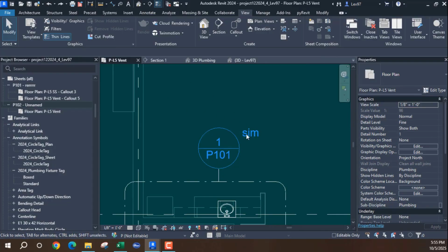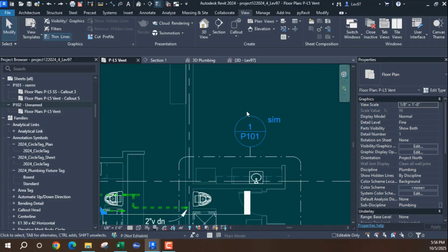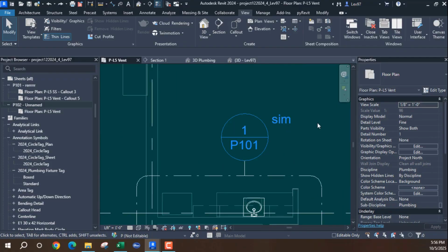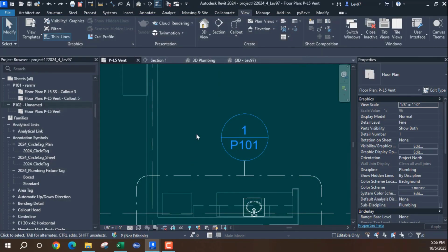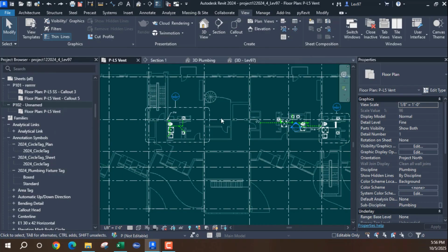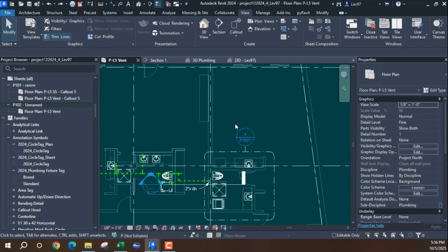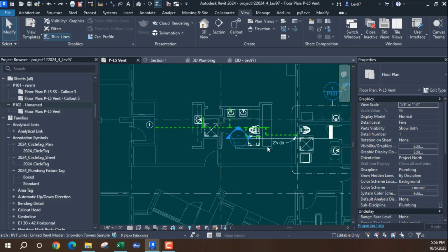So you can do whatever you want to do with this, but it's telling you that it's a reference. You can change it to REF if you want, but similar, or you can change it to whatever. Or I think, can you erase this? Let's see if we can not put anything here. Delete. Is that going to work? Yeah, it works, but you don't want to do that, because you have two P101s, and that's not too smart. Okay, so you can name that whatever you want.